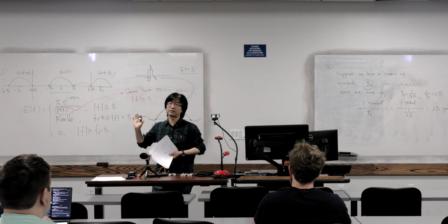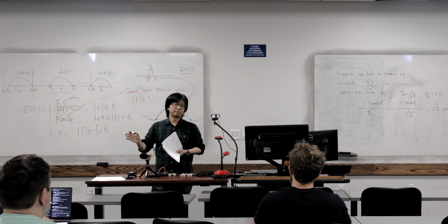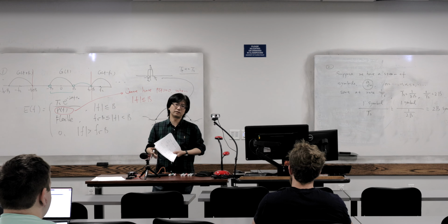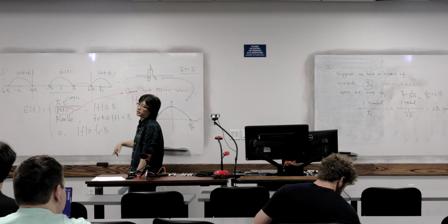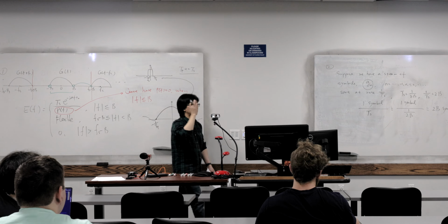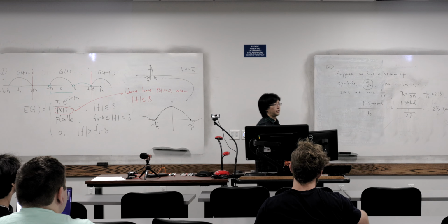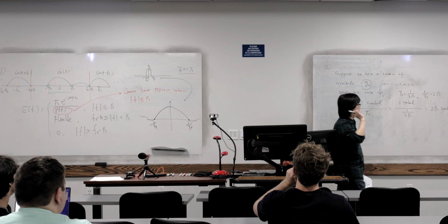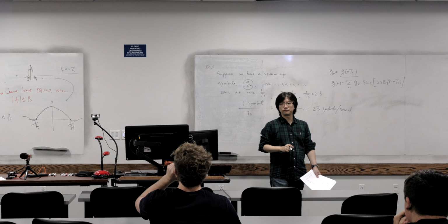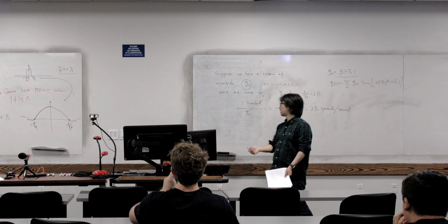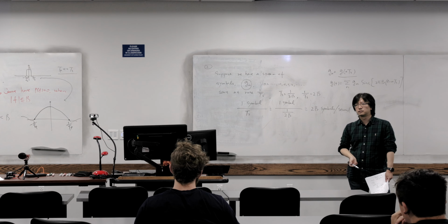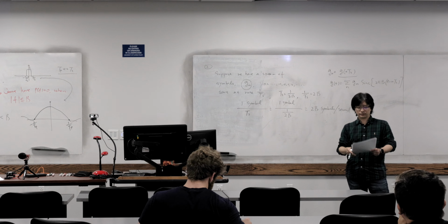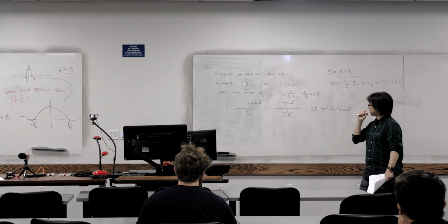We can make it more rigorous by using some concepts from information theory, which we're not going to discuss right now, but intuitively, this is how we characterize it. We assume all Gn are different and independent, so every Gn carries one symbol of information. If I have more bandwidth, we transmit more symbols, and more symbols mean more information. Is that clear?